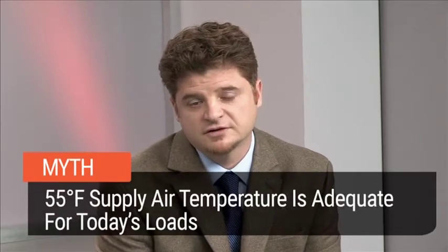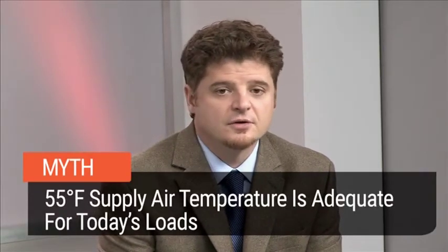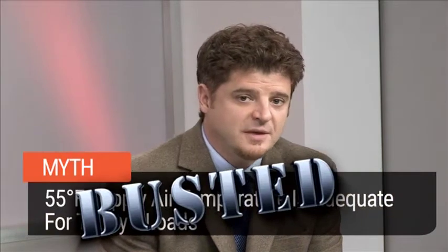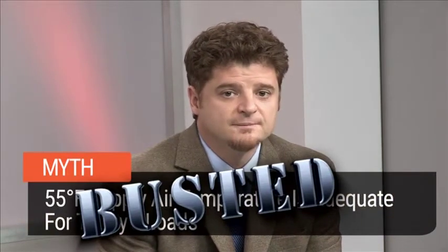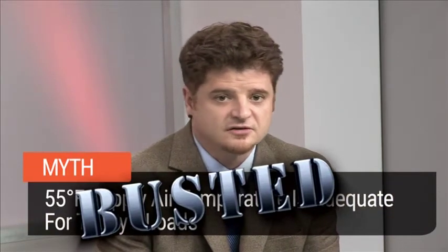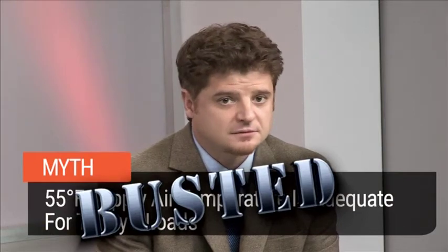So is it true that a 55-degree supply air temperature is adequate for today's loads? No, this myth has been busted. To maintain comfortable humidity levels, we need to consider the discharge air condition and its impact on the space, and not just the discharge air temperature.